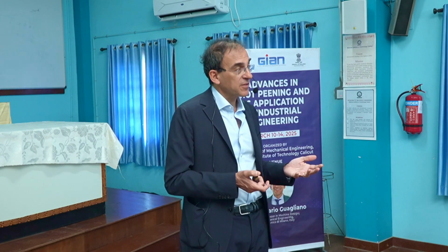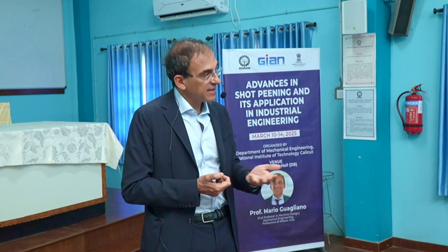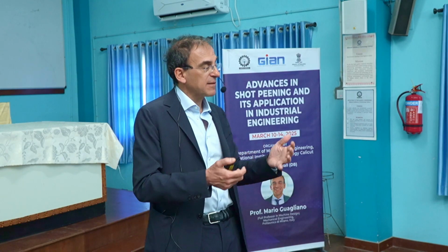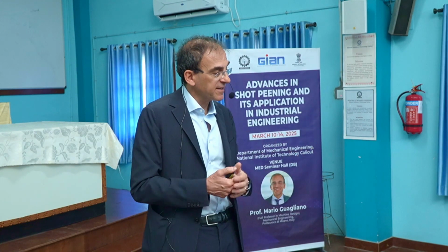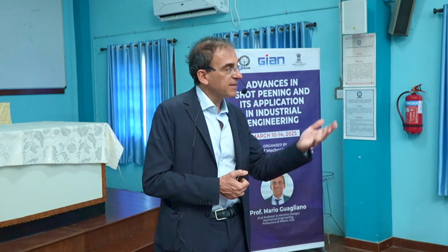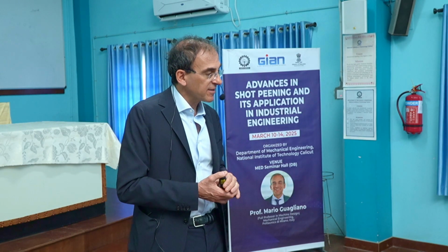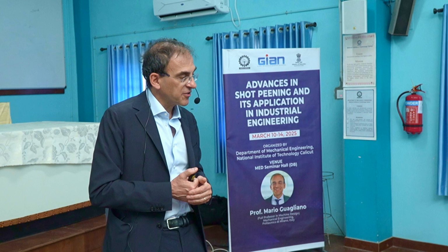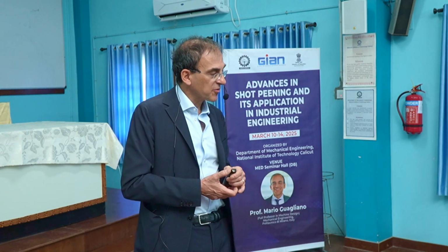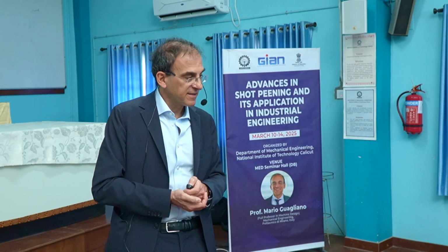The speed of the shot, no need to add that if the speed is larger, the indentation will also be larger, and so from a theoretical point of view, the number of impacts we need for getting the full coverage will be lower. And the impact angle is also affecting not only the area, but the shape of the impact area and the impact area itself. So this impact angle is another factor affecting the coverage.